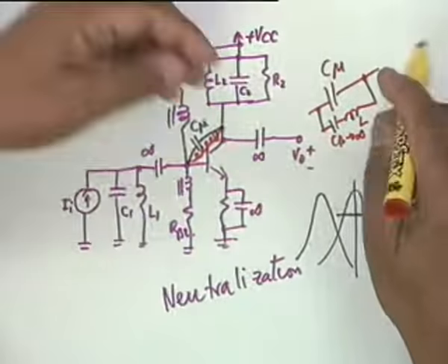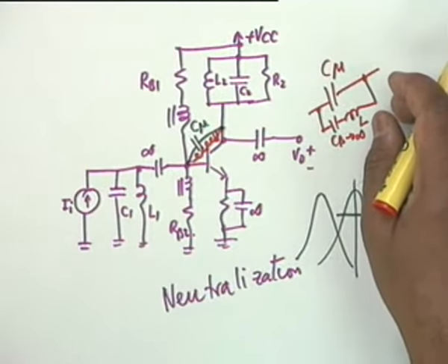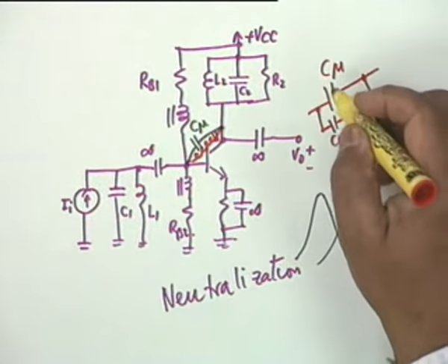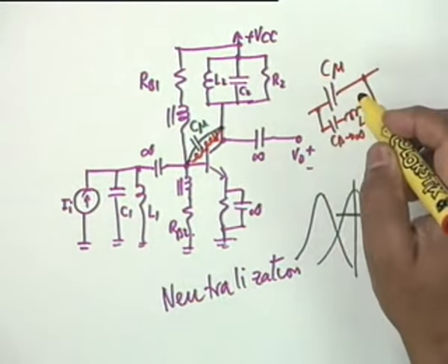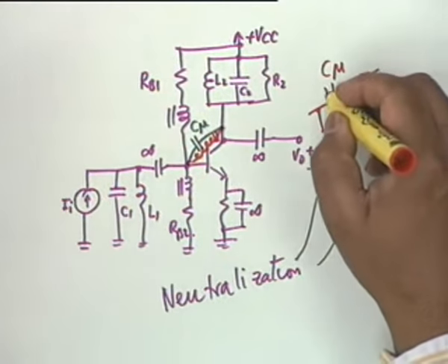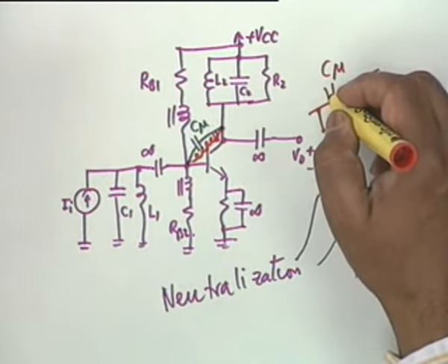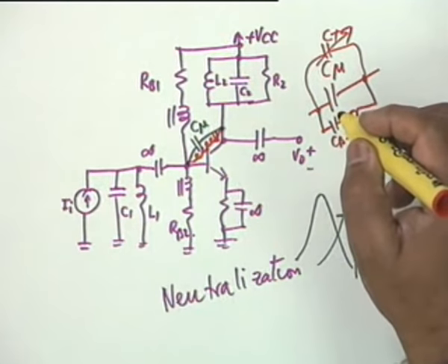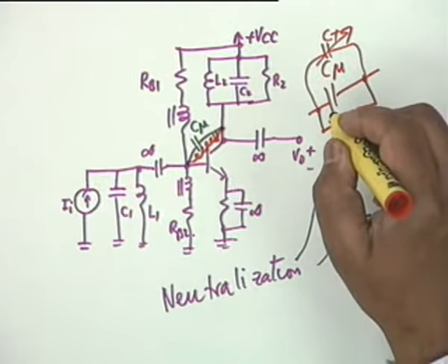So what one does is take the available nearest value of inductance, connect it. Then obviously C mu, we cannot adjust it, C mu is internal, but we can always increase its value by using a trimmer, CT, and adjusting a trimmer. A trimmer adjustment is much easier than adjustment of an inductance.